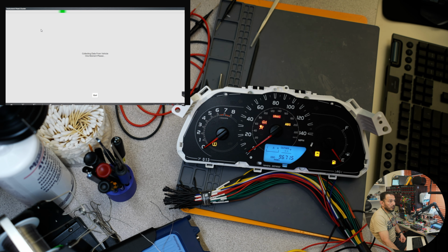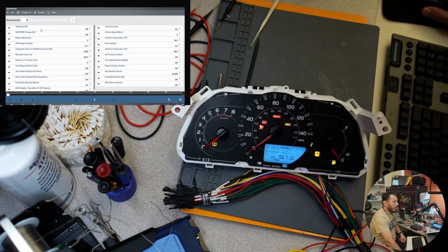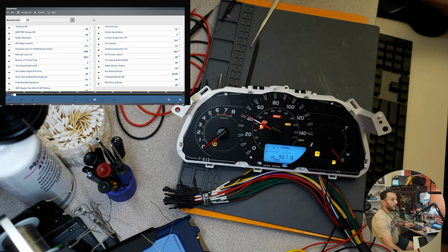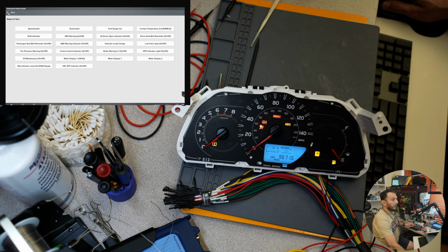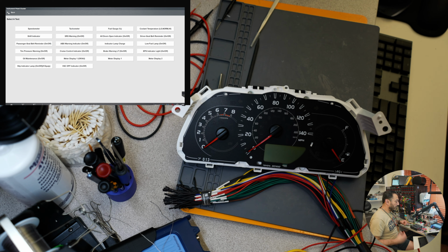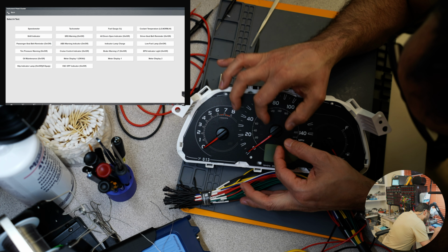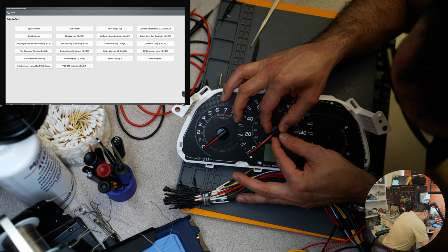All I need is the speed, because that's what we need to make sure is set properly. We're going to click on plus, and that's going to set 40 miles an hour. And this is where we're a little off. So we're going to exit, turn the cluster off, and we need to reset the needle. It has to go down a little, and I can definitely see now that it's a little off.